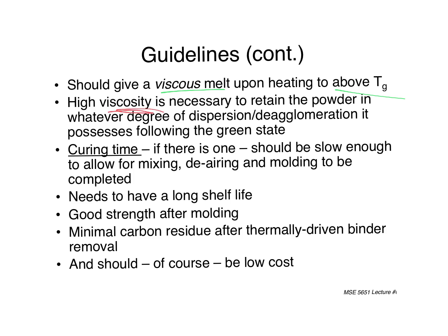High viscosity is necessary to retain the powder in whatever degree of dispersion or deagglomeration it possesses following the green state. And so we, unfortunately, are stuck with high viscosity polymers. We can't use just something like floor wax, low molecular weight paraffin or polyethylene. We have to make it high enough molecular weight that it has the right type of strength and also gets in between the particles.